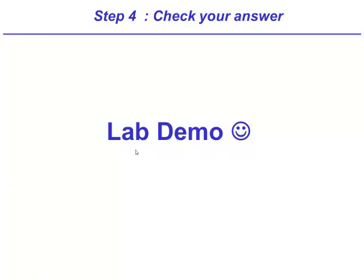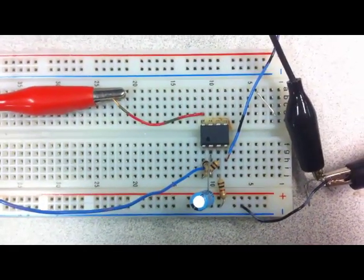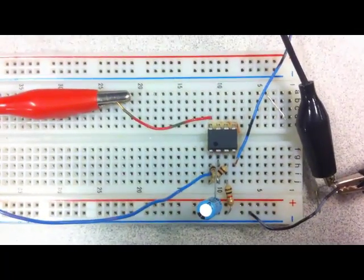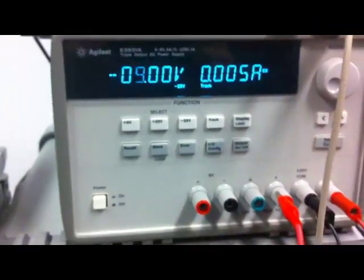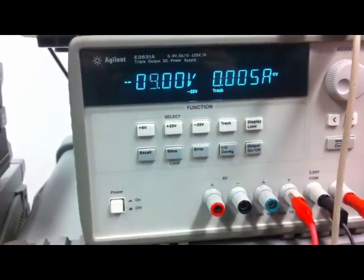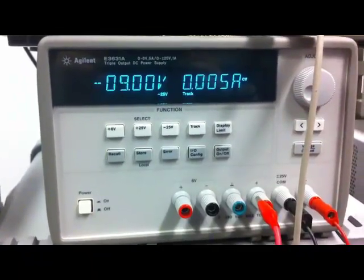Exactly, Amir. So it's lab demo time. So here is the lab demo. As you can see, we've set up the TLC277 op amp to make a relaxation oscillator. You can also see the resistors and capacitors set up. Over here with our DC power supply, we're supplying rail voltages of positive and negative 9 volts, as you can see. That should give us a rail-to-rail voltage of 18 volts.